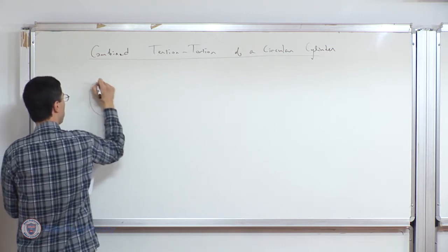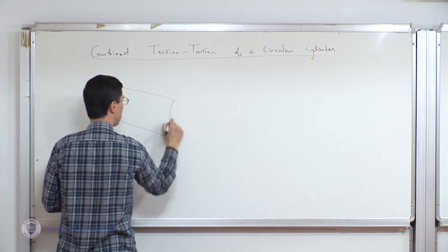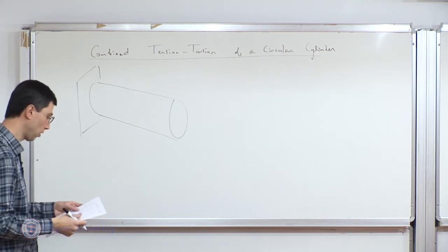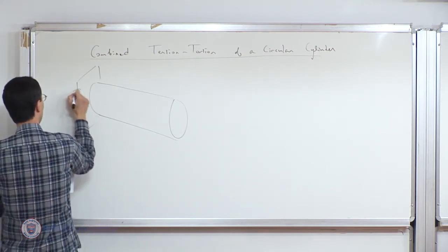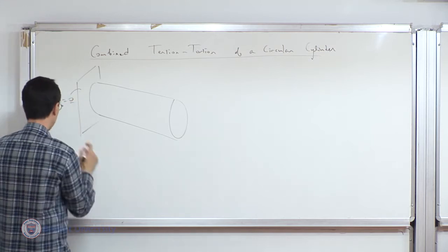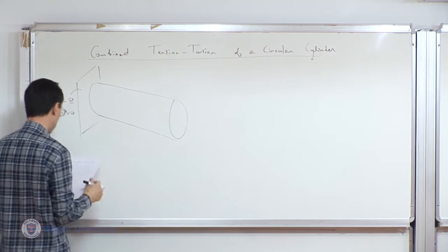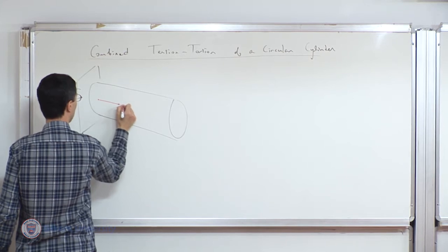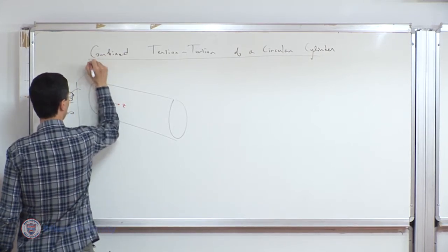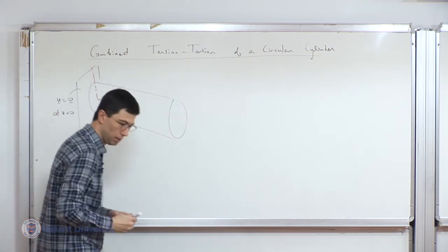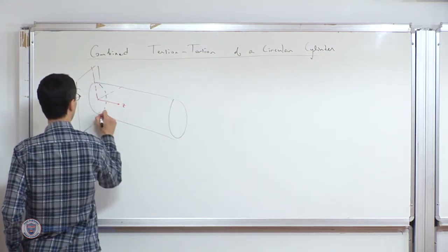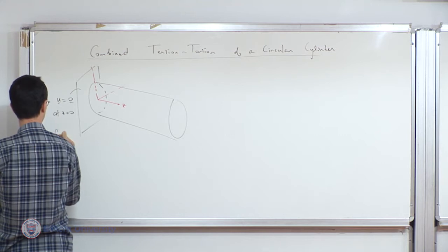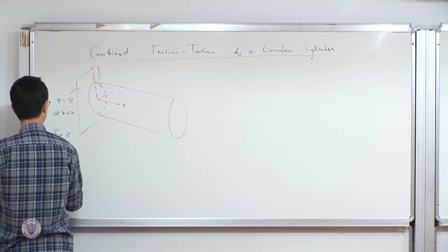So suppose, remember this problem we considered at the very beginning of the displacement-based solutions to demonstrate how the method works in a context that we are very familiar with. So we had a cylinder. We had displacement prescribed to 0 at the left end at z equals 0. So that was for us the z-axis. Additionally, we had no body force, and we omitted accelerations.